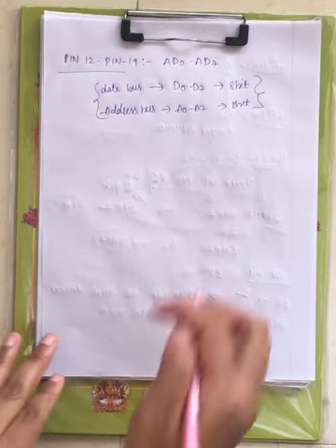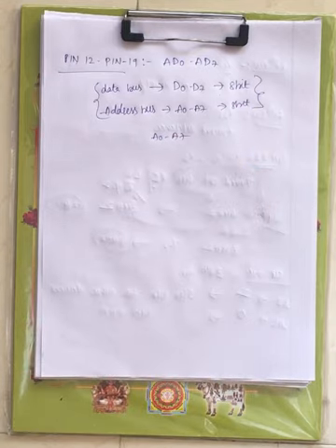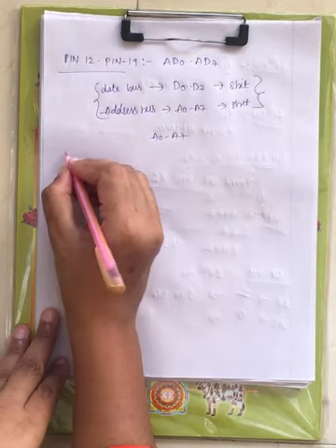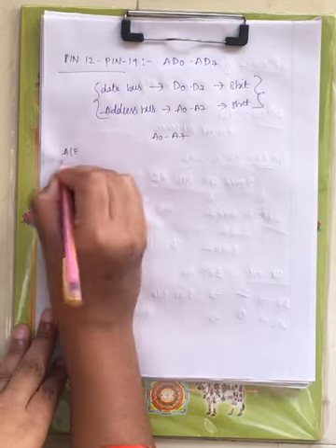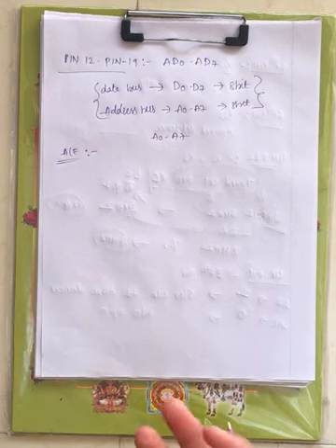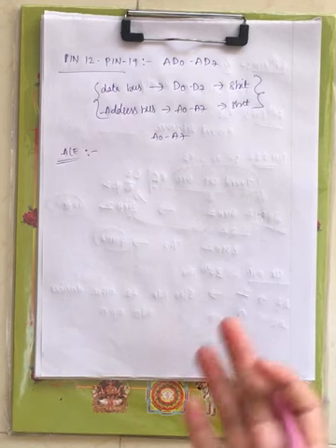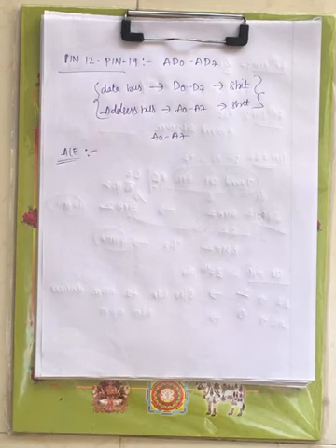Now I want to transfer only A0 to A7 through this bus. What I have to do is use the address latch enable signal. Based on this signal only you can transfer whether it is address or data through AD0 to AD7.